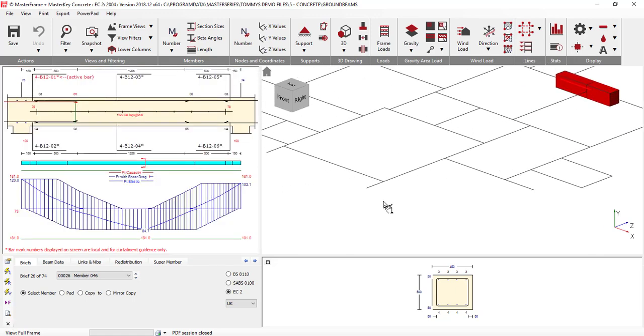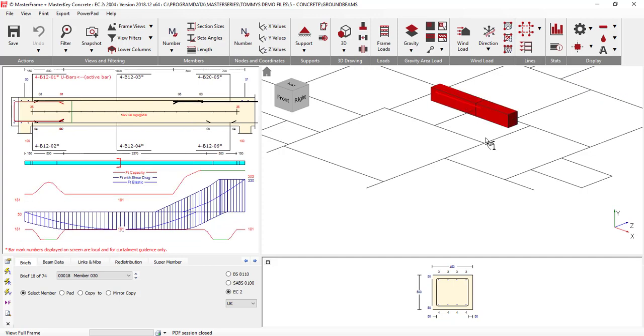Now obviously we cannot use this method of releasing the torsion if these cantilevers are not resisted by what I call a back span, but just coming out sideways, because that does require the torsional resistance of that supporting beam, and you would need to do that. So it's not always the case, but in here you have this facility.